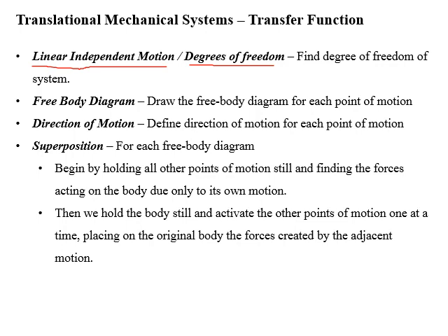After defining the number of equations, we will draw free body diagram for each point of motion. Now after drawing free body diagram, we will define direction of motion, in what direction that point of motion is going to move. After defining the direction, we'll use superposition principle.